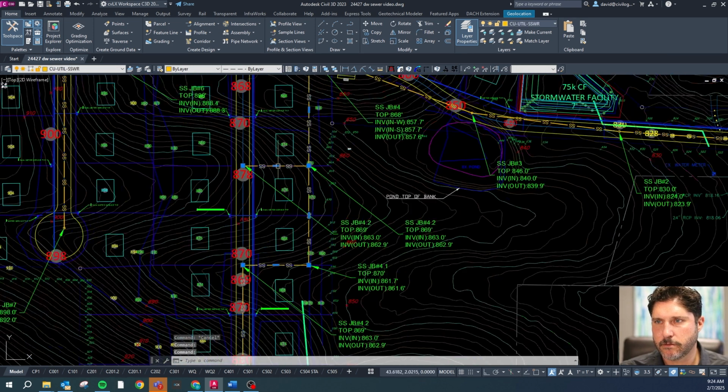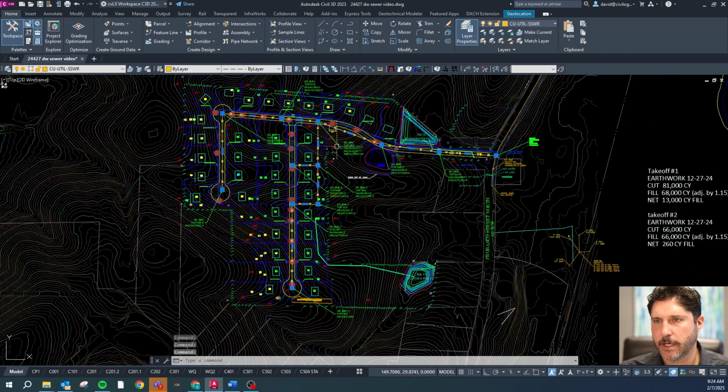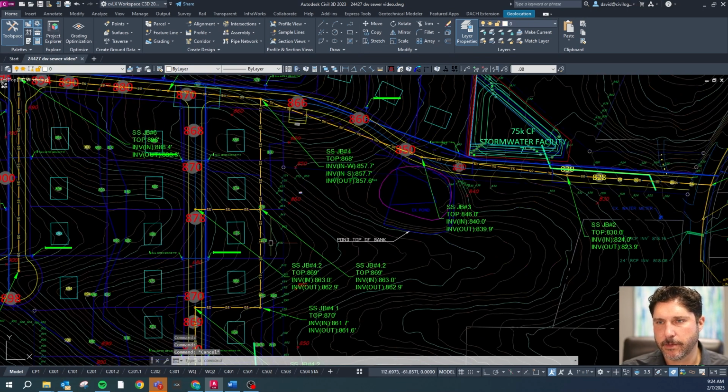These lines, maybe we feel like the S's are too big. If you want, you can change the line type scale to 0.7, and I do that a lot. I think that looks a little bit better. Okay, so let's figure this new manhole out.